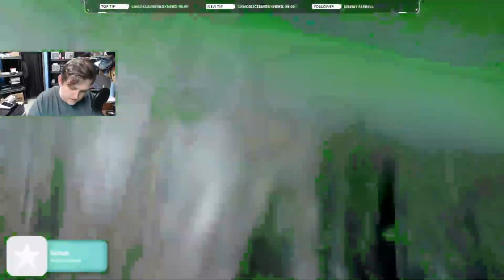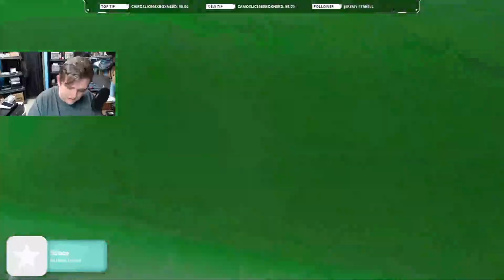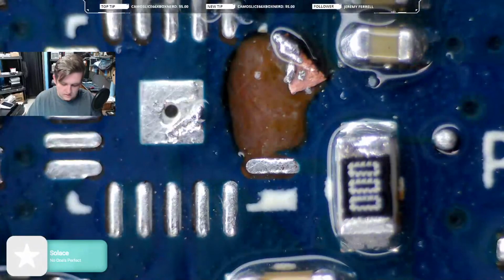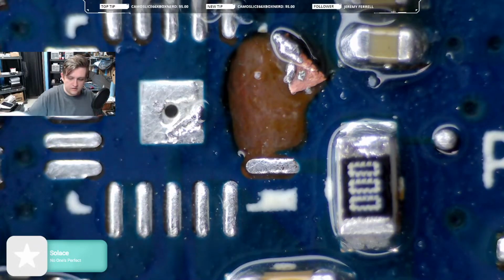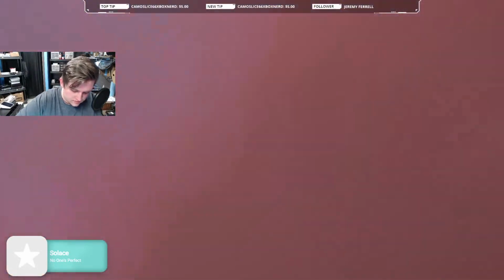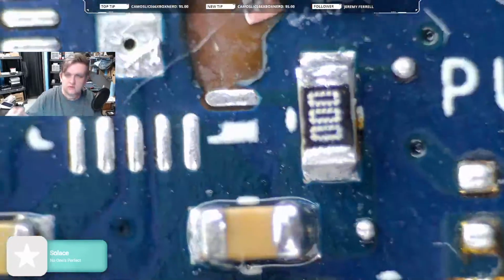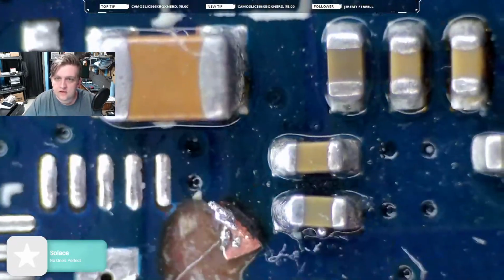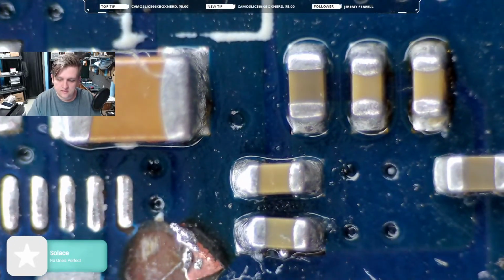Sometimes when you're brushing, after you've soldered a spot up like this, you can loosen a connection and, as you're brushing, knock a component off or something. So it's good to check the surrounding area. All right, so that looks pretty good, and you can see the trace line.